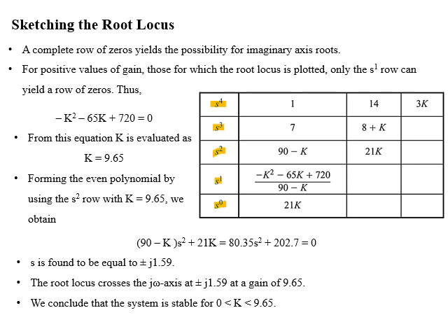We will place the coefficients of the characteristic equation in the first row labeled S4, skipping every next coefficient, and all the skipped coefficients will be placed in the second row labeled S3. For further rows, we will use the rules of the Routh table to complete it.